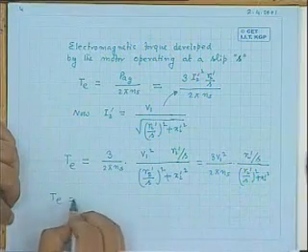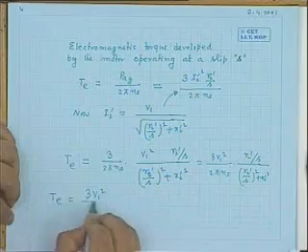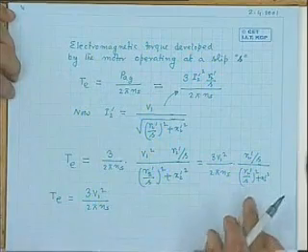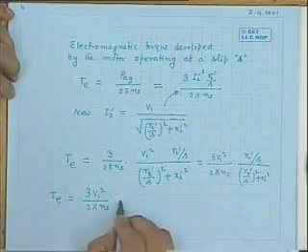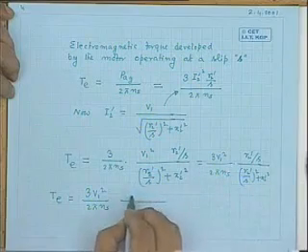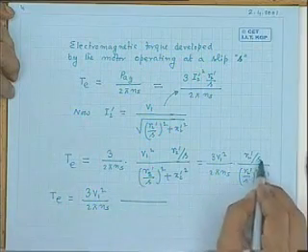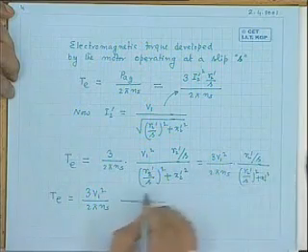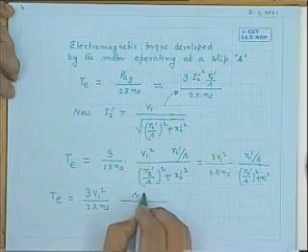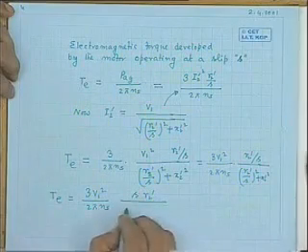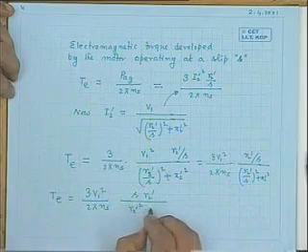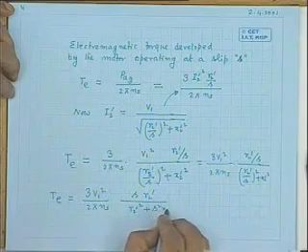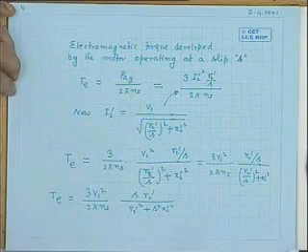Now what you will do is this: TE equals 3V1 squared by 2 pi Ns. You multiply both numerator and denominator by S squared, some simplification. If I make any mistake, point me out. So the numerator will be S into R2 dashed, and below it will be R2 dash squared plus S squared X2 dash squared.